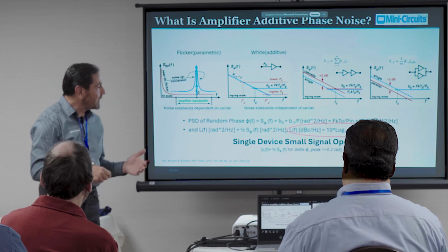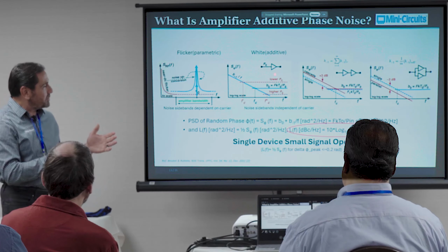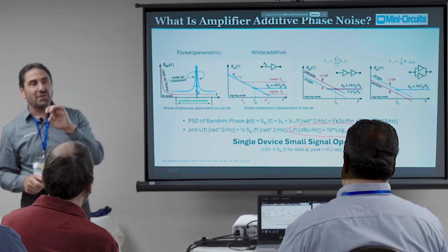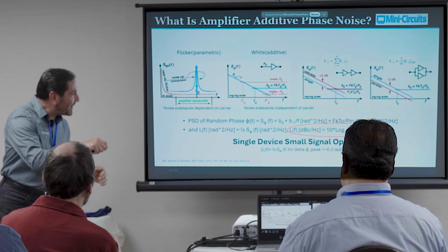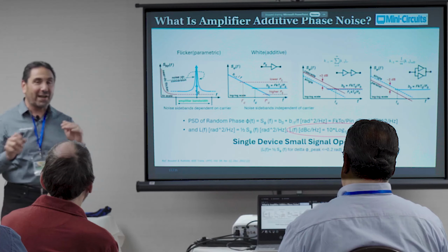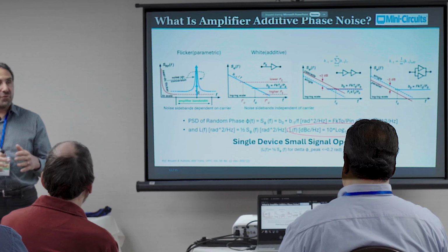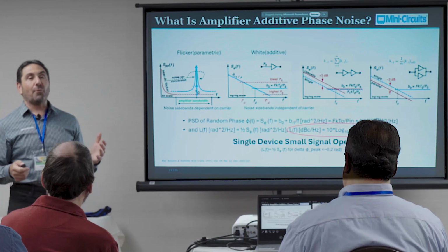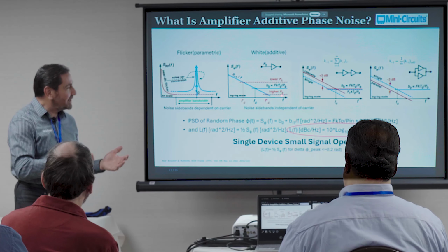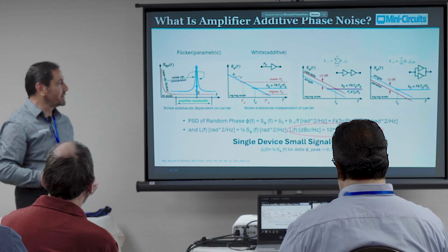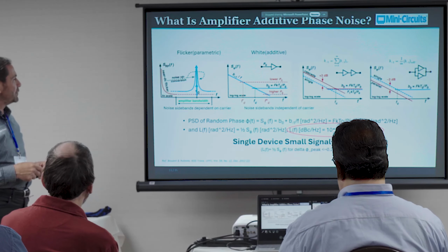So this is important because that's why I was focusing so much on input power, because depending on what your input power is, you're affecting the power spectral density in the white noise region. So if you're arbitrarily just assuming a power, you could be up here. But why not operate here and maybe put a pad afterwards? So we'll go out and talk about that in more detail.